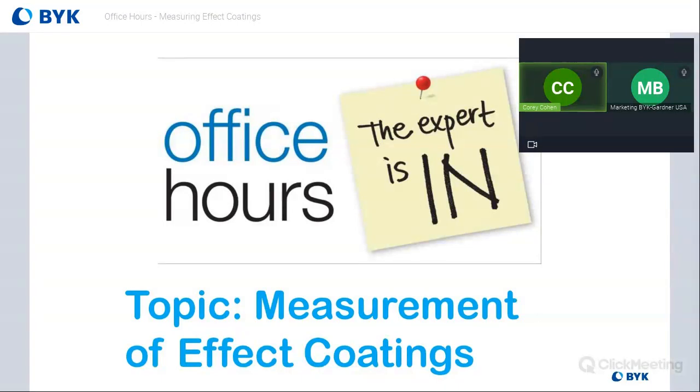One issue you can get is if that flake is disoriented, if it's not in the same direction as the plane of the coating, if it's turned at a different angle, that can sometimes result from a dry spray or an overly wet spray. So sometimes the moisture content of the coating when it's being sprayed can affect that.